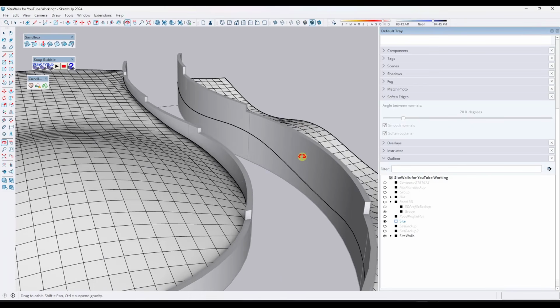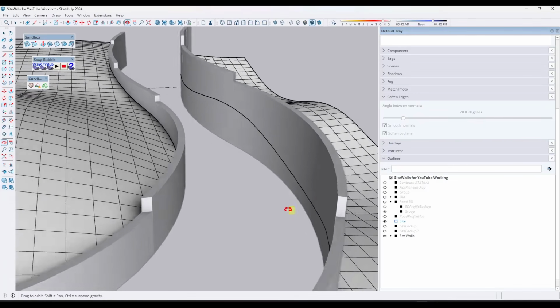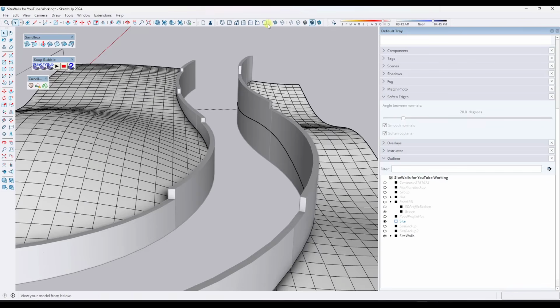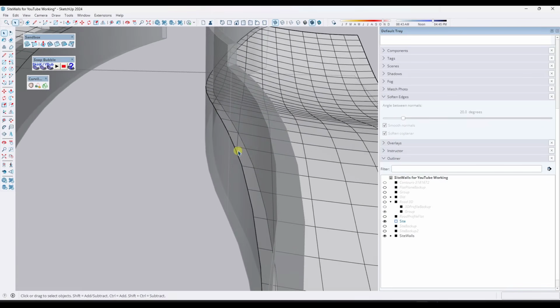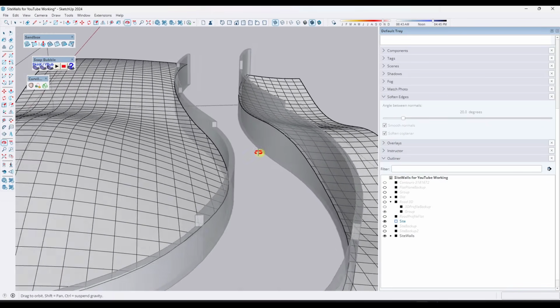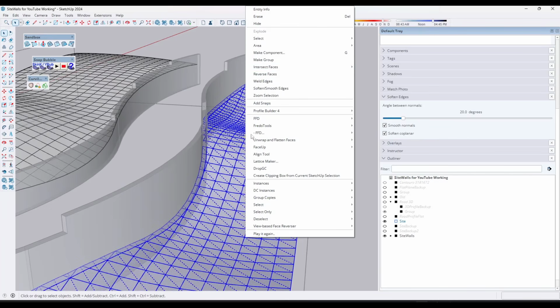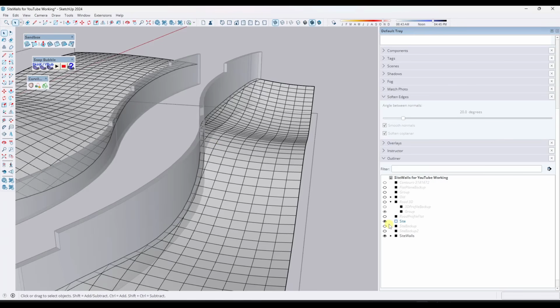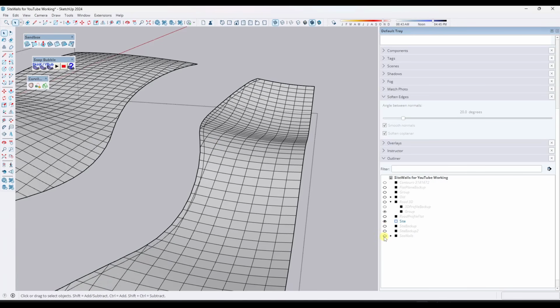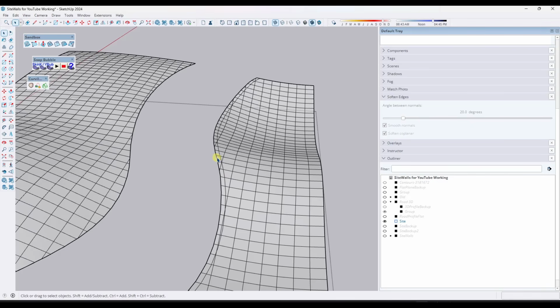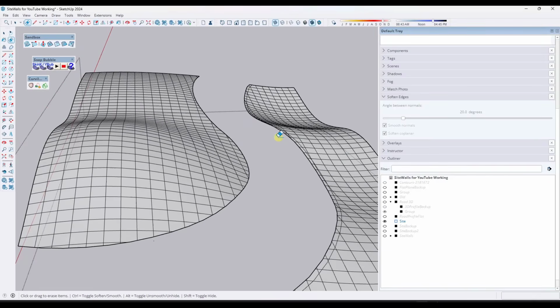And there's a couple ways you could go about fixing this. You could intersect that with your model, because if you look at this, notice how your wall is intersecting with your model right here. So you could just triple click on this whole thing, right click and intersect faces with model. And then if I toggle my site wall off like this, you could come in here and erase all of those edges. So that's one way to go about this.